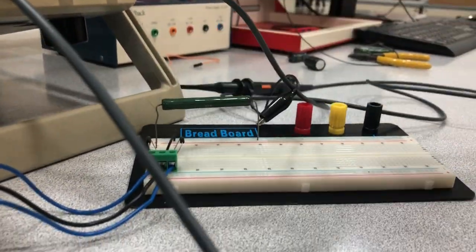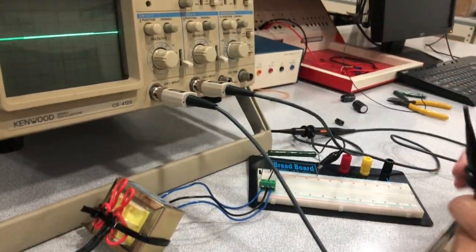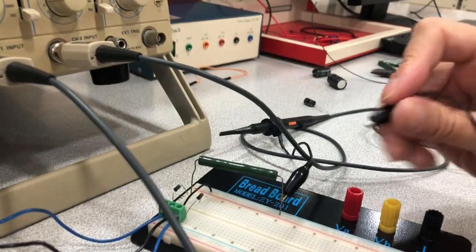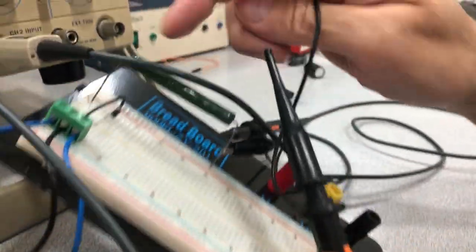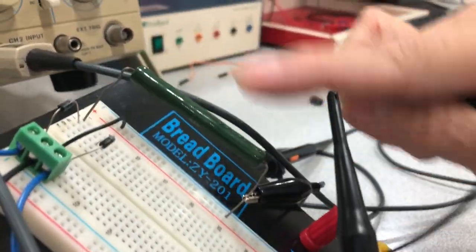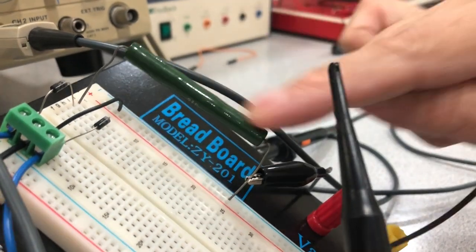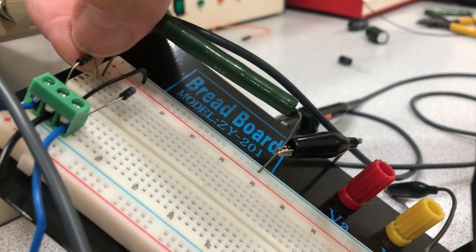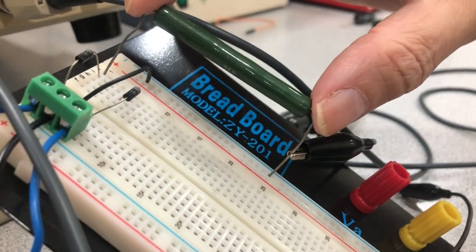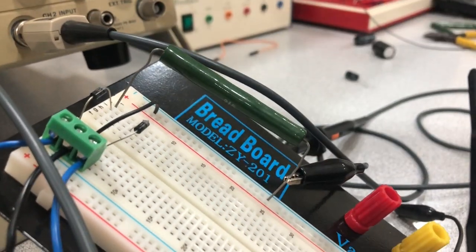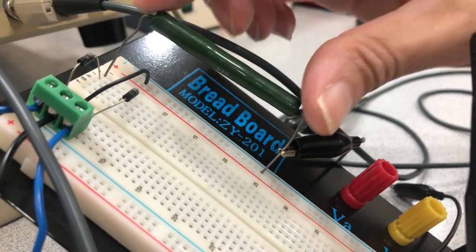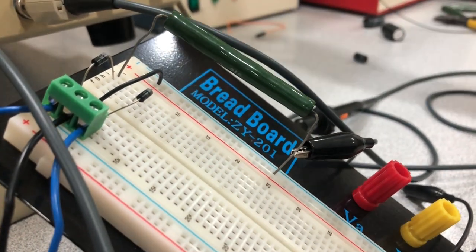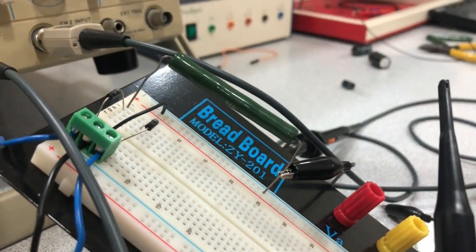The first thing I'll do is take this channel 1 and put it on the ground. Notice where the load resistor is. This resistor is at least 5 watts. God knows we couldn't really tell for sure, but it's a much larger resistor. Usually small resistors are as big as this diode. So this is a higher wattage resistor. It can dissipate heat more. It can handle more power dissipated in it, and it dissipates it to the environment, to the air.